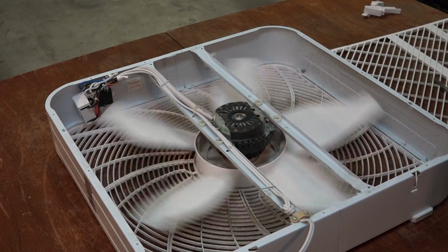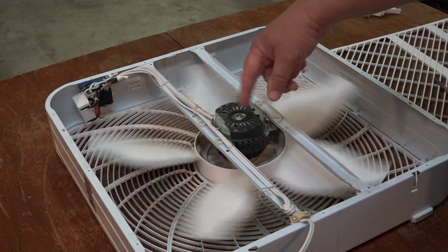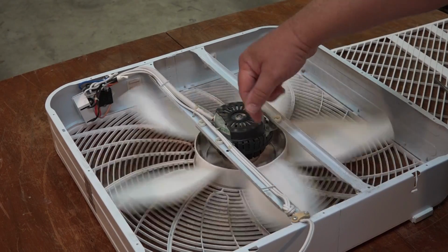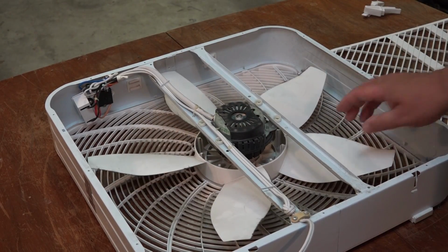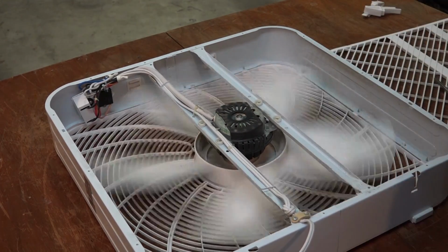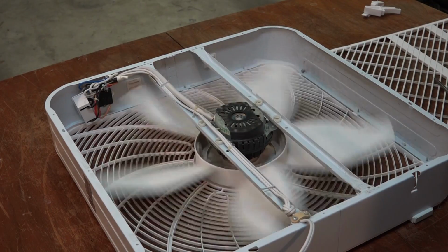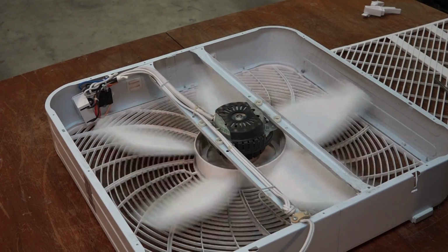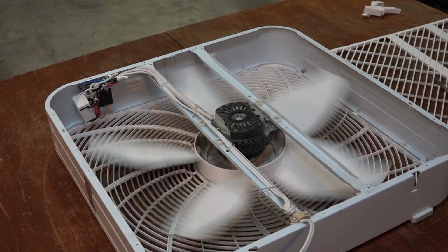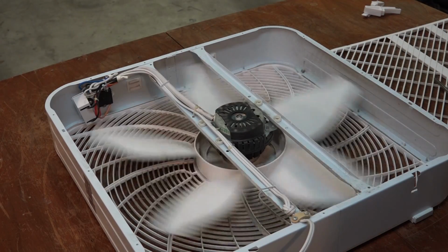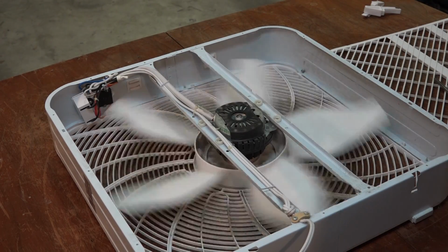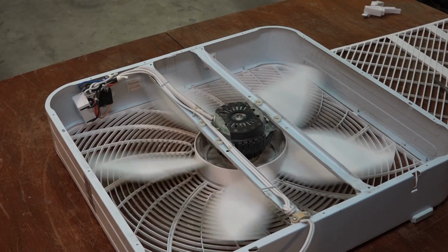Right now we don't have a rotating magnetic field, but we've got the rotor spinning just because I started it by hand. If I stop it, nothing will happen. And if I spin it the opposite way, it'll continue to spin the other direction too, because again, it's a synchronous motor. It doesn't care which way it spins. It'll spin either direction when your secondary coil has no power.